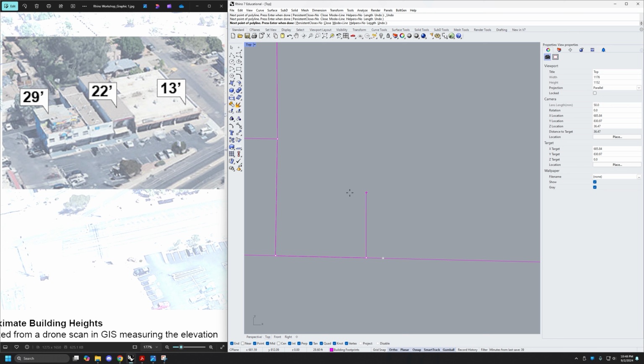So for example, if I'd done 30 feet in this direction and pressed tab to lock that, you can see if I hover my cursor over on this side, since I've got my other constraints keeping this line in place, I don't necessarily have to click right here, as long as I click where that pink node for the endpoint is. Hopefully this is making sense. So in this way, I was able to click on the corrected distance, but I wasn't actually on this line because it was wanting to snap somewhere else.